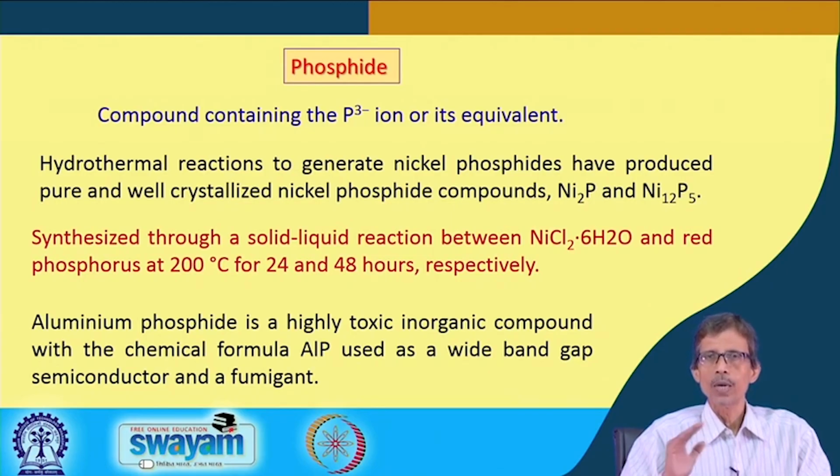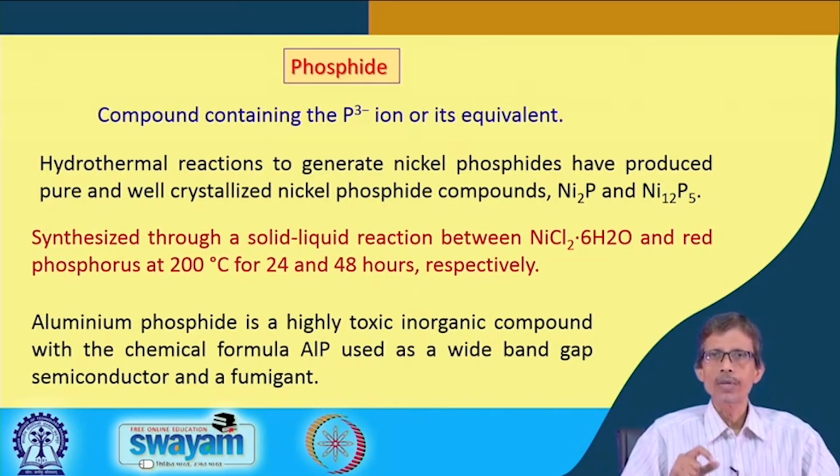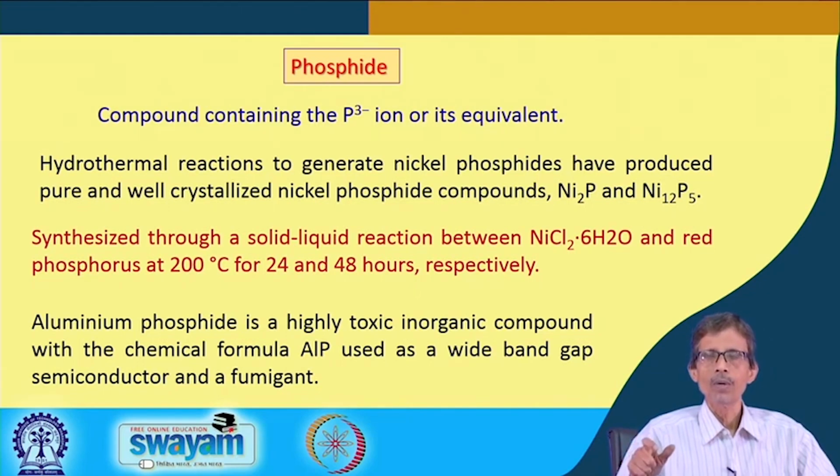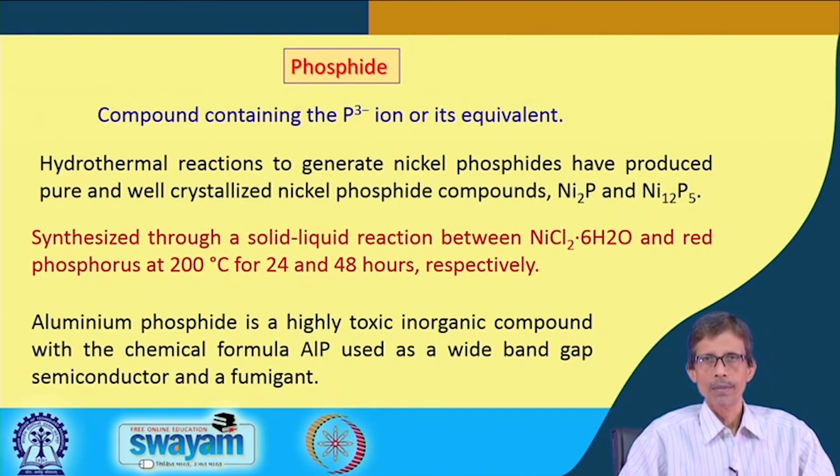Again, as you moved up from room temperature to 200 degree centigrade, you can go down from 200 degree centigrade to room temperature in an incremental fashion, such that you go down to room temperature in different steps. You can have different monitoring, different programming for that temperature drop from 200 degree to room temperature. So, after some time, say 10 hours or 5 hours, you will be reaching the room temperature condition for the reaction vessel.